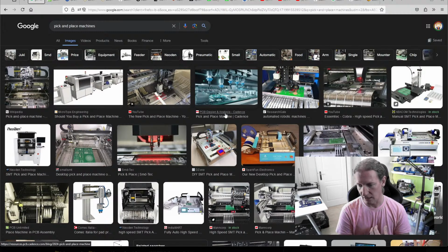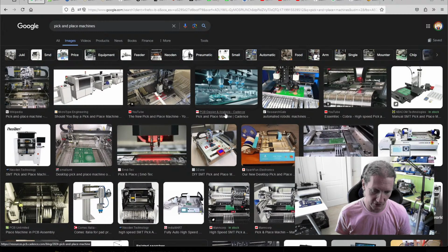Some machines that are out there have 2 cameras and a camera switcher board. So you only have one input to the computer via USB for the camera, and it switches the input from one source to another. This is very common on the cheaper machines. It's cheaper to have one chip and a video switcher than it is to have 2 capture chips. Plus, there are also implications for the number of USB ports and streams and all this kind of stuff. So camera switching or 2 cameras is another requirement.